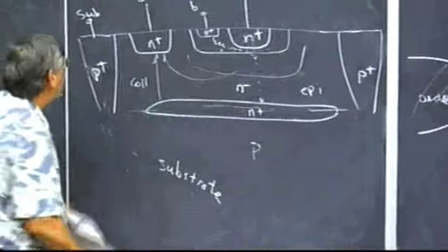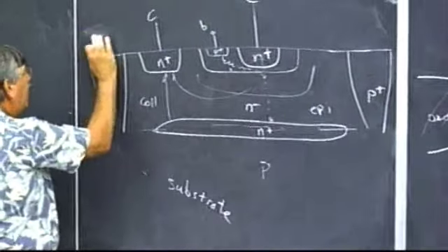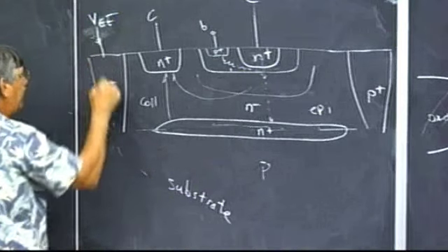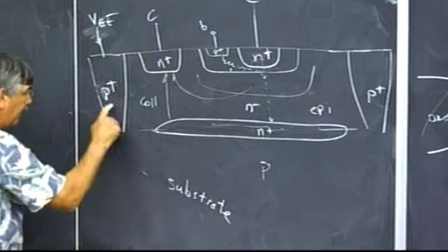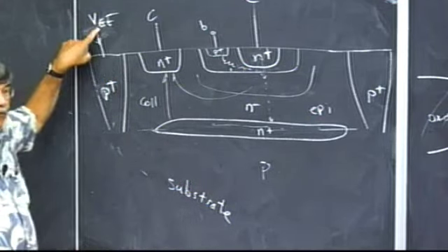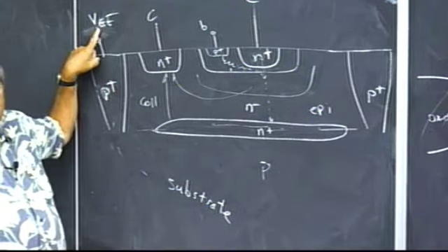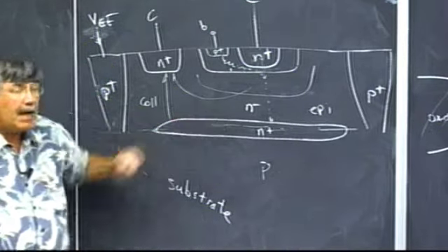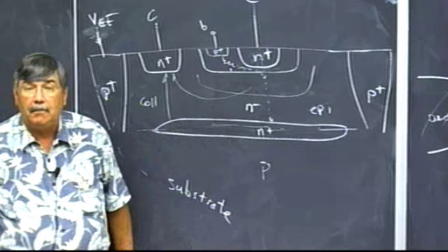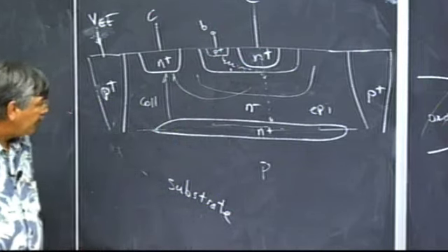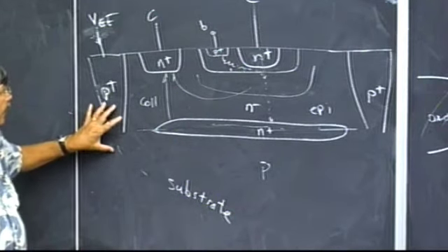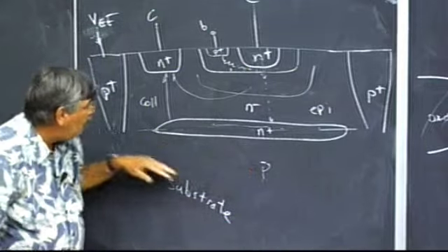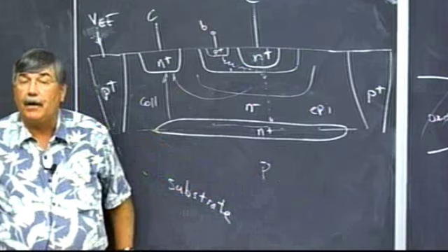And what I'm going to do, and now we can start some circuits, I'm going to put this at the most negative potential in the circuit, call it VEE. This is the P-type substrate. If this is the most negative DC voltage in the circuit, then there's no way to forward bias this junction. It's guaranteed all the time to be reverse biased. We hope. That's the plan. And so if this thing is at VEE everywhere, then that'll reverse bias it. And so we needed a P-type region for isolation.